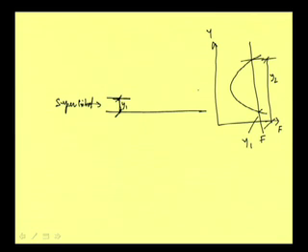Now, somehow here the tailwater depth is this much, and we are writing this tailwater depth as y2 dash, not y2, because this tailwater depth will be governed by some other condition at the site. Maybe we are putting some barrier here and increasing the depth, or maybe by a sluice gate on the upstream we create this y1, but the downstream uniform flow will be this much. So, due to various reasons we can have the tailwater depth. This comes from the physical process, and that is y2 dash.